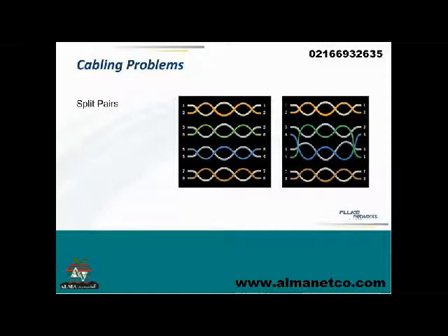And what you get, especially with Ethernet, which uses 3/6, 4/5 pairs in lower speed Ethernet, is a transmit and receive pair twisted together and another transmit and receive pair twisted together, and it will not work. Or, as I mentioned, if the cable's short enough, it'll work intermittently. And so this is a very tough problem to deal with.